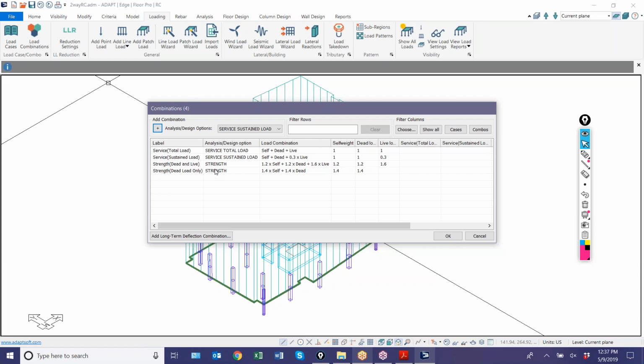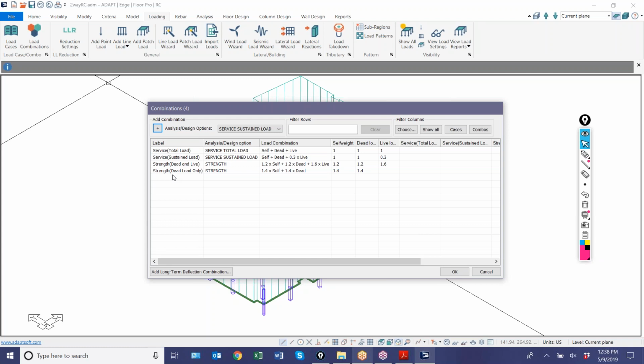The question was, well, if I have a model that has other types of loads, it might be lateral, it might be other classifications, I may need to have several more load combos. So how do we get those into the model? And the short answer is you have to build them in the model. Once they're built one time, you can use the IMP exchange to actually import load combinations between models. We have this internal tool, again, that has not been released, that would actually calculate, or let's say populate, all of the load combinations into a model.